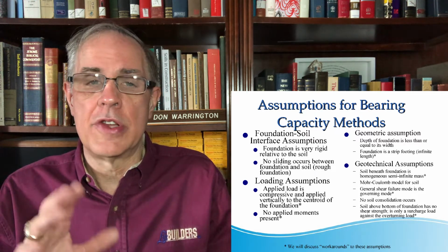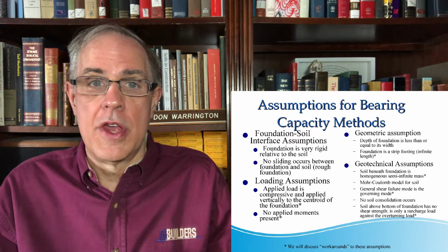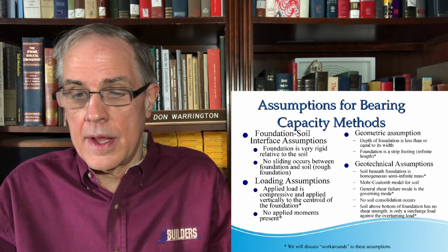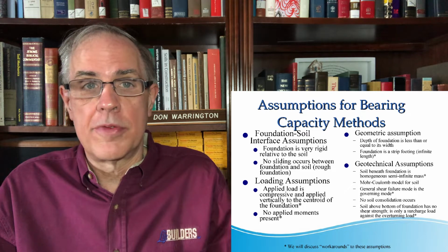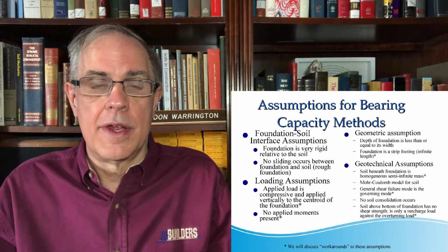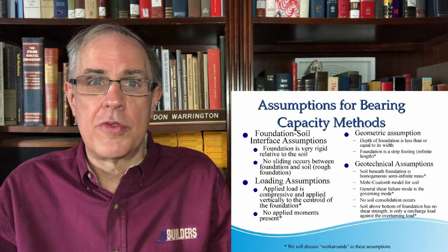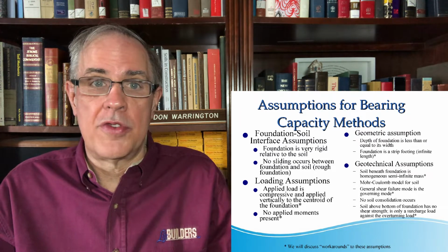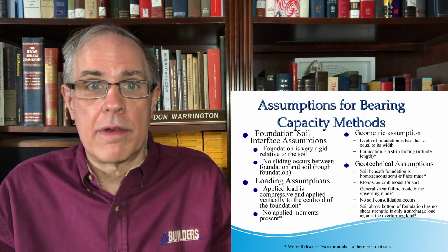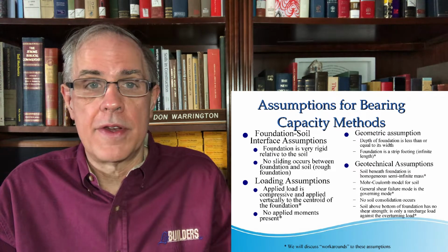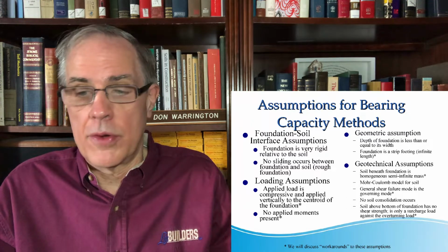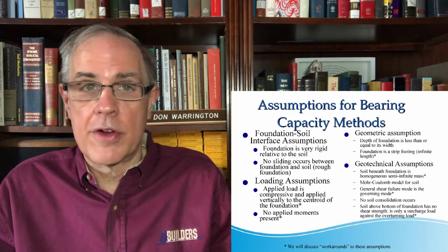We assume a flexible foundation, because for a rigid foundation, as you recall, for infinite strips there's no lower bound solution, since you get infinite stress in the corners right off the bat. So we assume that there are no sliding curves, which was true.